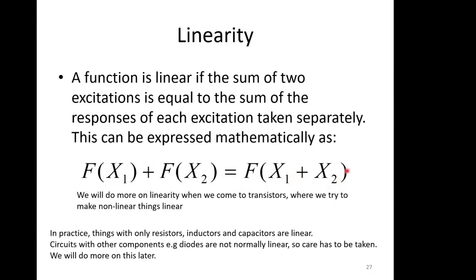And the interesting thing there is if you've got a complicated circuit with lots of sources, say x1 is a source and x2 is a source, maybe x3 and x4, what you can actually do is divide it into little problems. You can say, let's only worry about source 1, and that's easy to work out. Then we'll make that one 0, and we'll worry about source x2 and work out what the answer is there. And we just add the two together, and that gives us the total complex function.